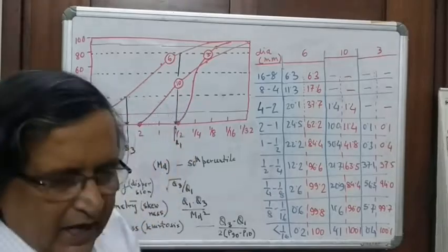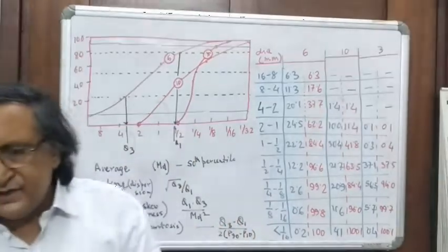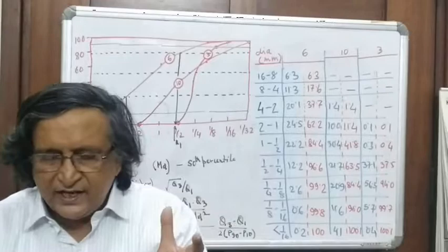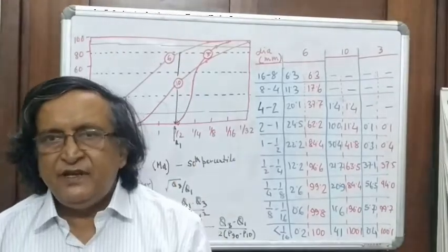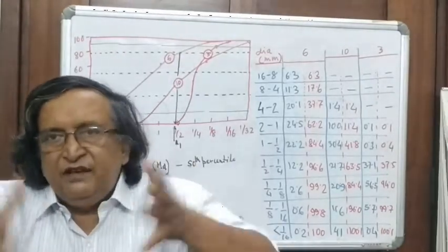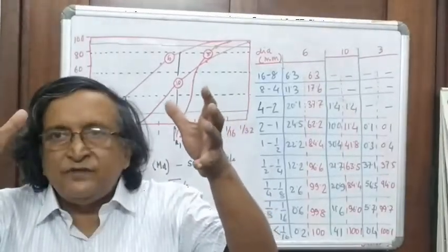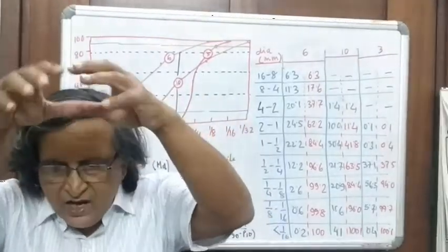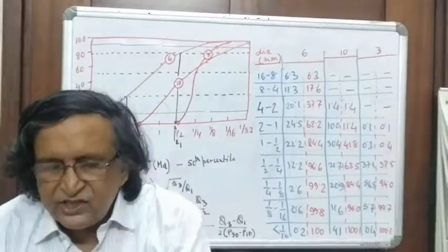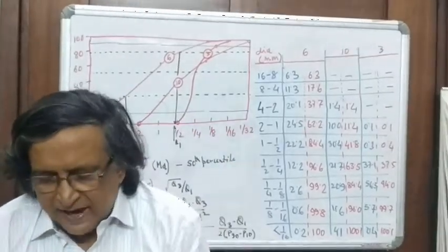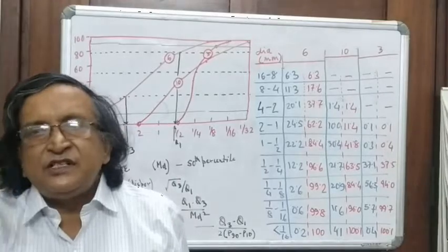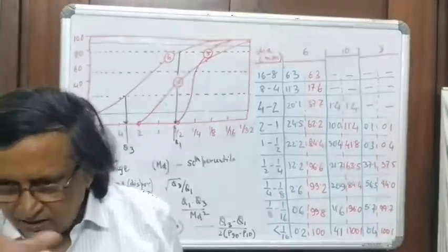I also told you in one of these early lectures that when you get a sediment, you put it under a sieve, and then you shake the sieve. If you put a known amount of the sediment on the top, when you sieve it, the sediments are graded and separated by pans of different sizes, and the sediment collects on the sieves.